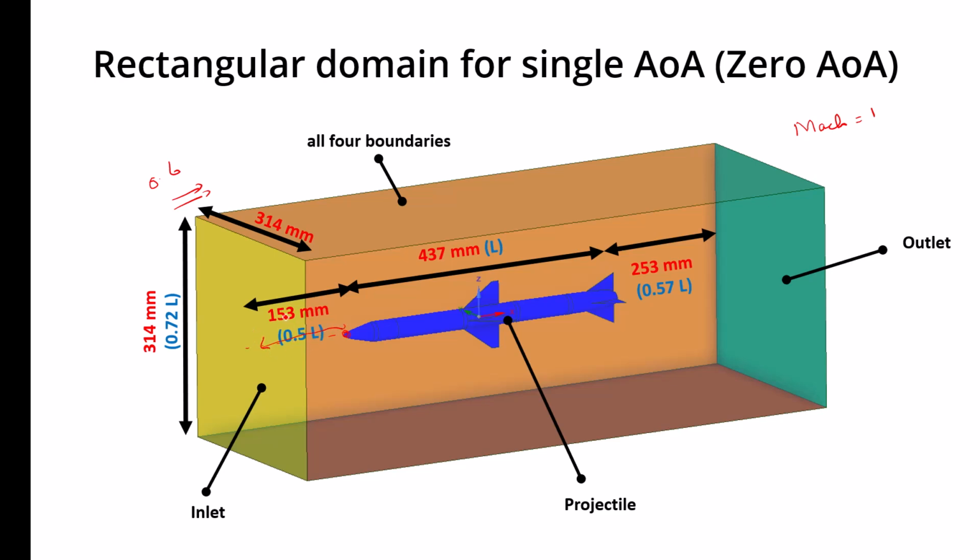But in the case of supersonic flows, this information does not travel at a higher speed, because the flow is already at a higher Mach number, like 2, 2.5, 3, 3.4, 3.54. Any Mach number more than 1 will be the same thing. So the information will not travel back to the inlet, and it will not affect any conditions on the inlet.